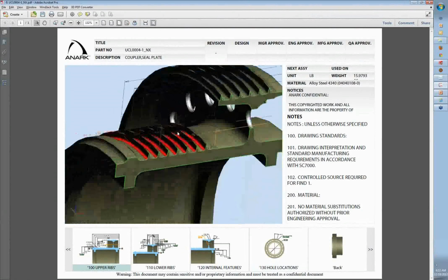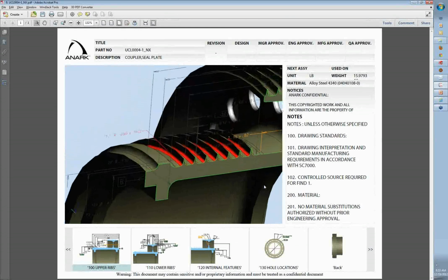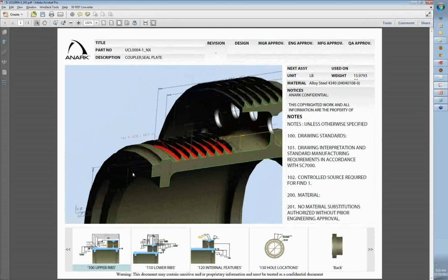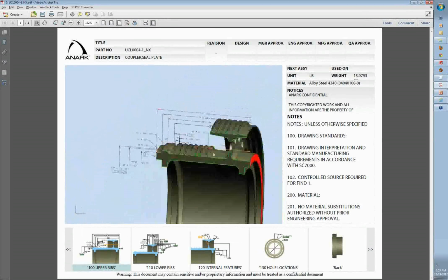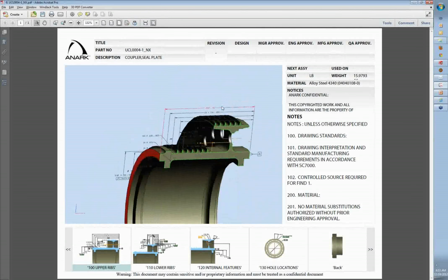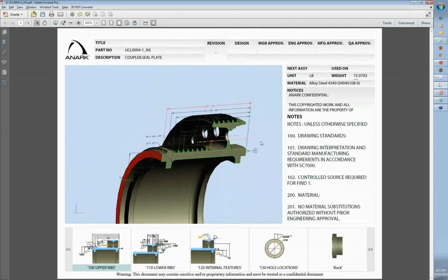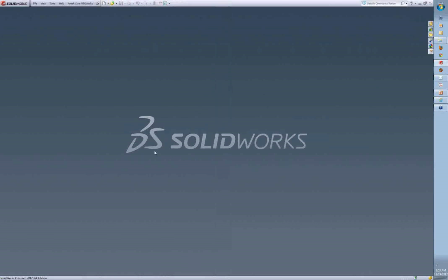Now, once again, this was published from Unigraphics, from NX. And we've got that same ASME Y14.41 visual response here. I can click on these datums or any of these width dimensions, and we can see without a shadow of a doubt, again, what this dimension is that the designer is trying to communicate. So there's a PDF document, and I'm going to close this now.